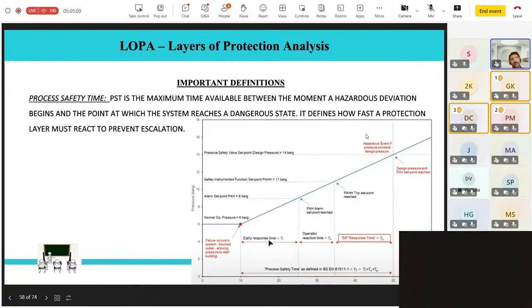So this is a total of 25 minutes. If that is less than the 30 minutes, then the system is inherently well designed, or safely designed. However, if any of these times are offset and it crosses the 30 minutes benchmark, then your system is inadequately designed irrespective of whatever integrity levels you are providing.